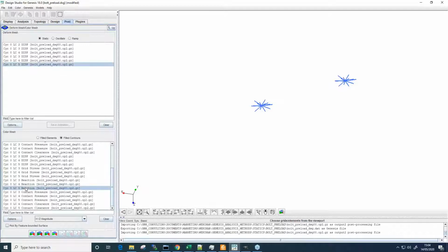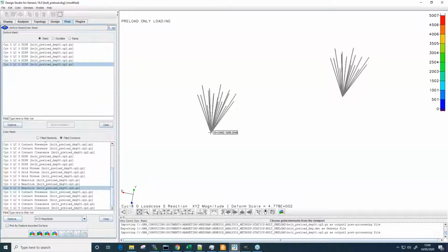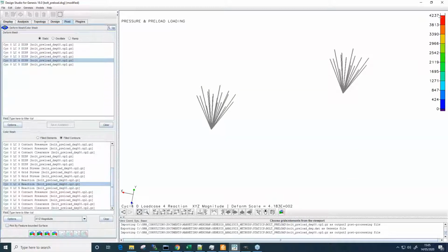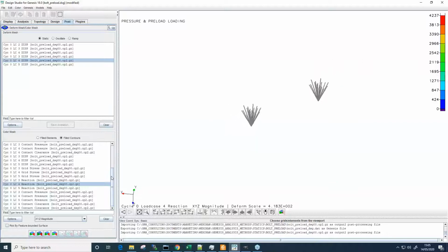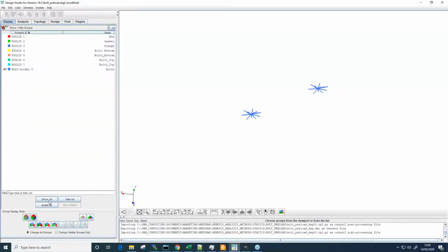If we take a look at this, what you see now is we've got the reaction force at that bolt control grid at 5,000 newtons. A little high at 5,006. Obviously some convergence in the contact going on there. But you can see that's our bolt preload. So what it's telling us is that by applying the pressure load to this vessel, the bolt preload is being overcome and it's reduced down to 4.2 kilonewtons as an output. So it's a useful thing to measure often when you're looking at such cases in the real world, is knowing what's happening to the bolt and its cross section.